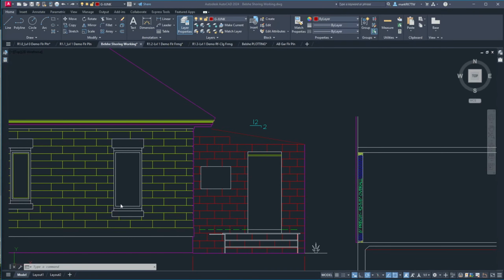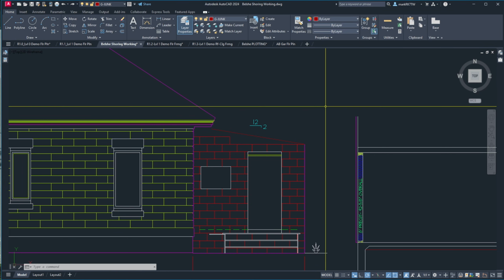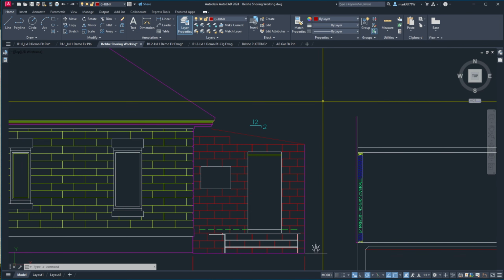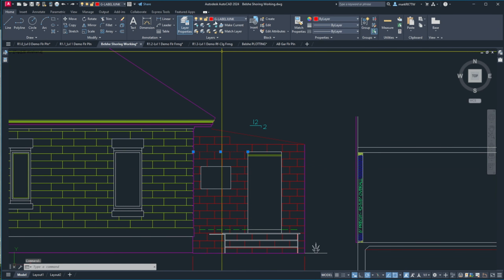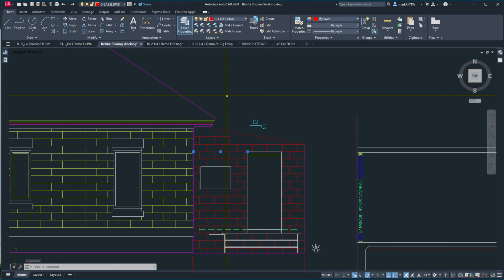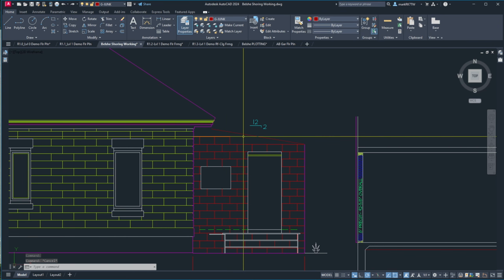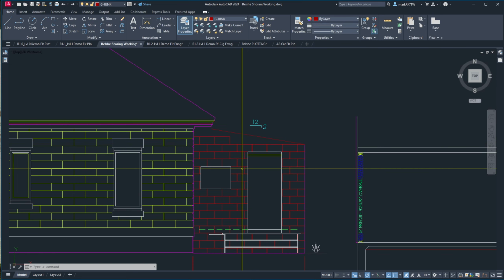The only way I know for Chief to isolate layers is to go into the layer display, check everything off, make it its own layer set with just one layer, and then you could do something with that layer. Well, here I need all these, which are temporarily on what I call a general layer or junk layer, but G for general. It's stuff that's for my own purposes as a designer and not stuff that I need for printing or for the client. But I need it now that I'm done with what I was doing in that case.